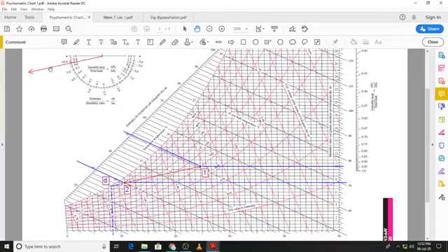That means this line over here in the protractor is parallel to line 1 2, and on the inner scale we have the sensible heat factor, sensible heat by total heat, so it is around 0.69. Sometimes we can move from the protractor into the chart, and sometimes from the chart to the protractor to read the desired value. That depends on the problem that you are solving.